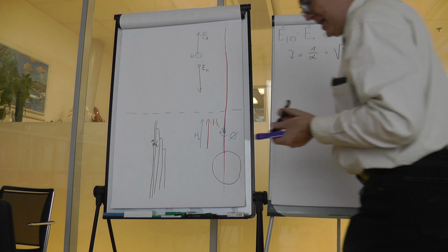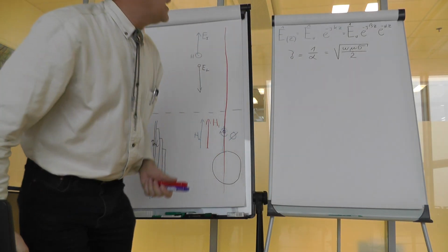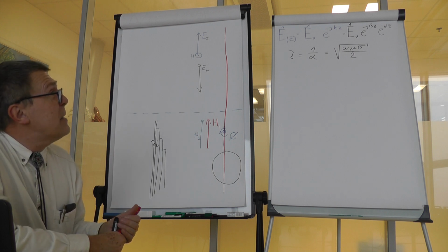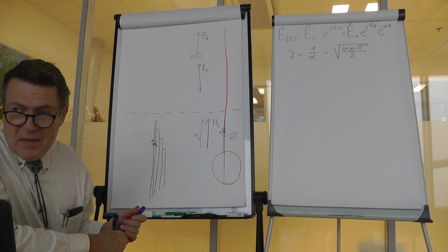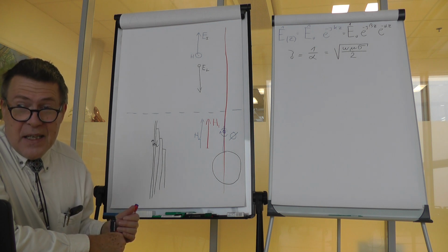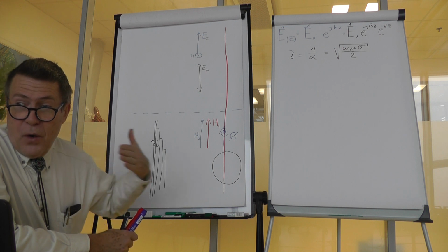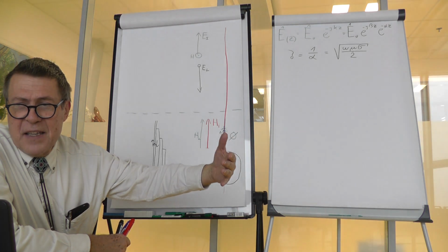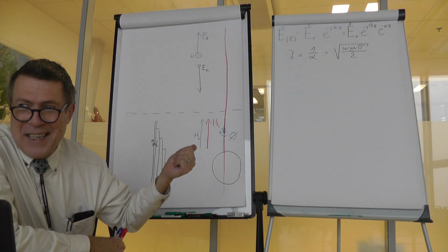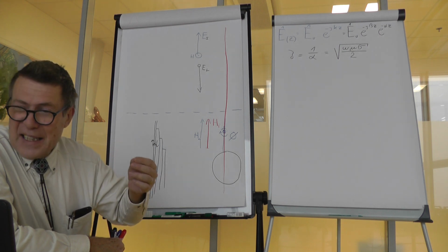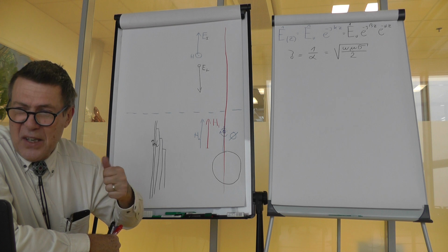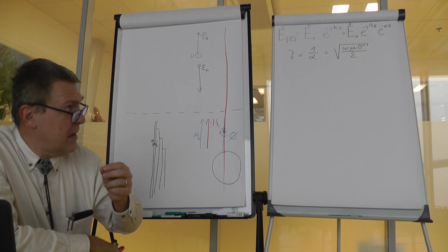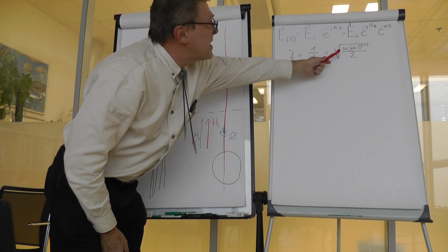And this is the depth of penetration, a very important concept, because it enables us to pretend that the current does not flow through the whole piece of the metal we have available, but it only flows in a thin skin, therefore skin effect, in a thin skin which is placed on the surface of the material. Now this skin depth clearly depends on frequency.